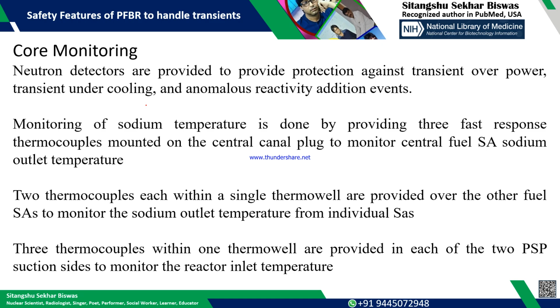The sodium temperature monitoring is done by providing three fast response thermocouples mounted on the central canal plug to monitor the central fuel subassembly sodium outlet temperature. There are two thermocouples, each within a single thermowell, provided over the other fuel subassemblies to monitor the sodium outlet temperature from individual subassemblies.